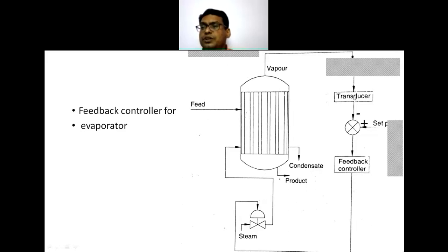Then a transducer, then comparator, feedback controller, and again going back to adjust the amount of the steam which is sent into the heat exchanger or the evaporator.